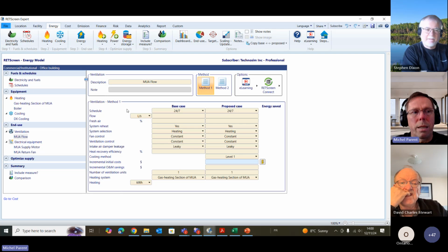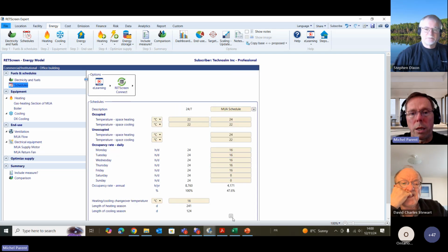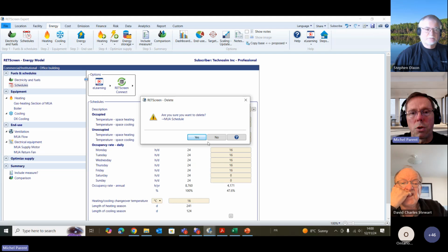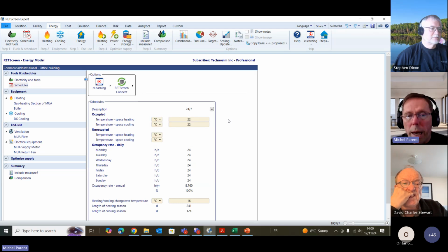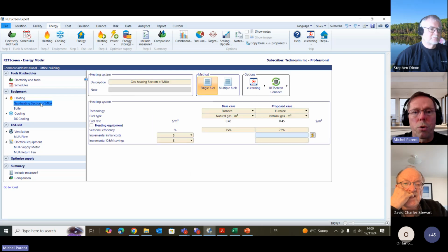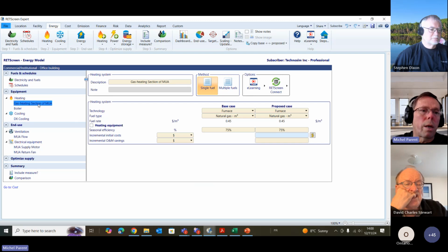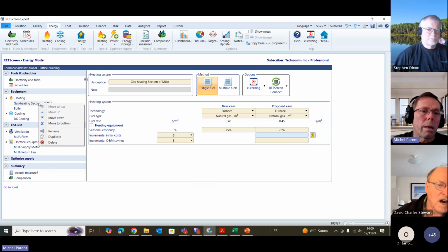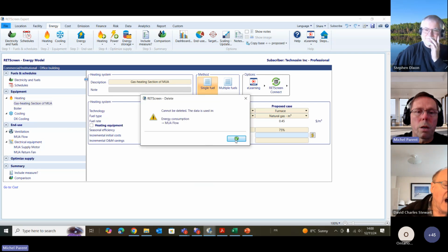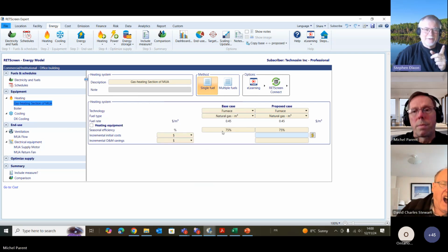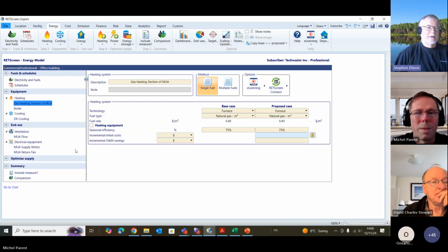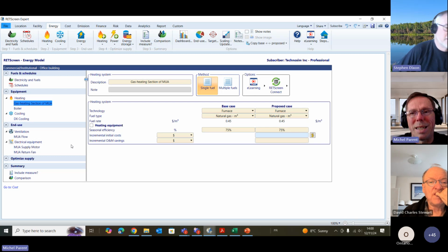So now I deleted it. So now I actually should go back into my schedule. I should be able to delete my schedule that I don't need, that MUA schedule. It's not a makeup air unit. So I was able to delete it. And I should be able to delete that boiler, that gas heating section that I do not need. And by the way, the way I do it, I select it and I right click and I delete the component. It's still called out in your method 1, because when you switch from method 2 to method 1, you're going to have to go over to the method 1 ventilation and change that to a boiler.